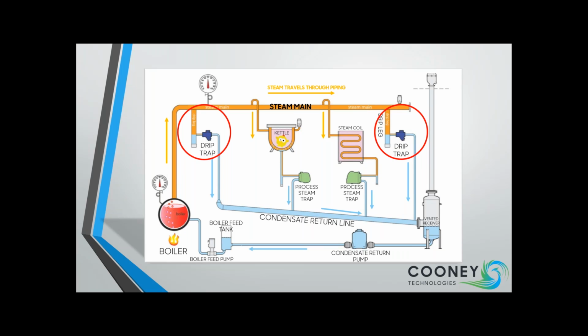Steam system damage can occur as a result of a catastrophic system failure due to water hammer. And it could also cause painful scalding personally and severe bodily harm or even death. I have personally been in mechanical rooms where steam water hammer, oh boy, makes you think that valves or equipment are about to blow apart. And believe me, that can make you want to change your diaper.